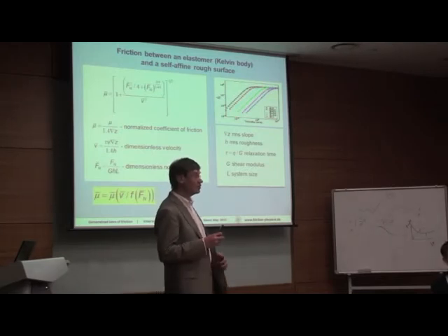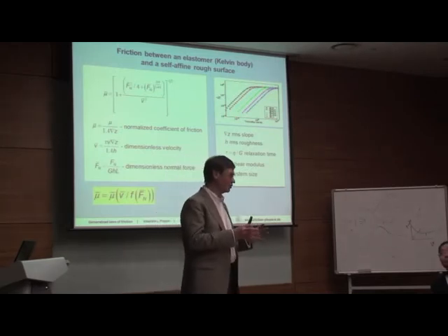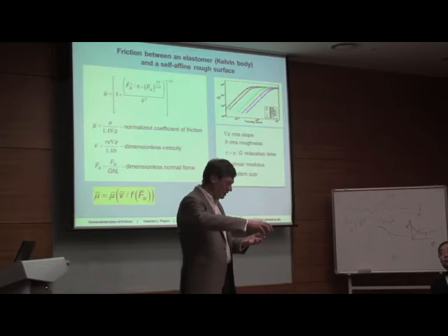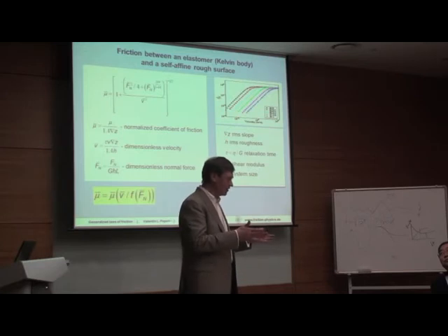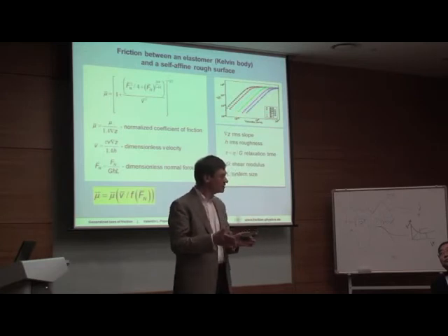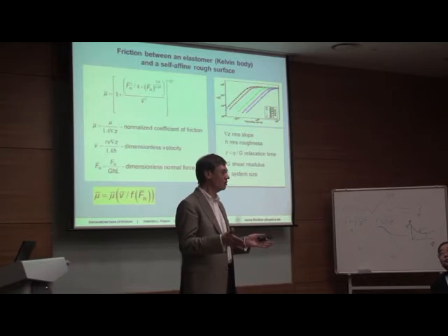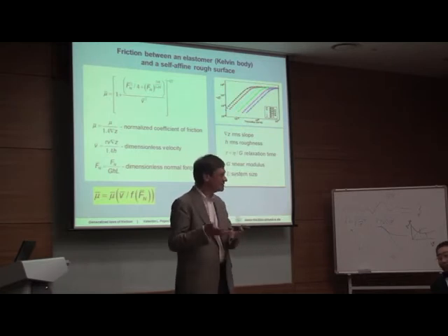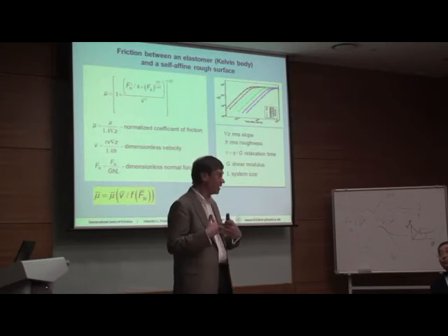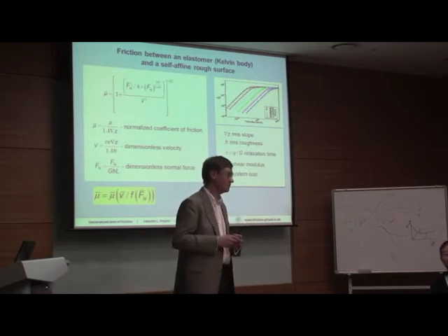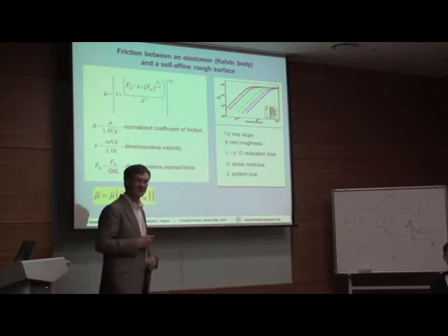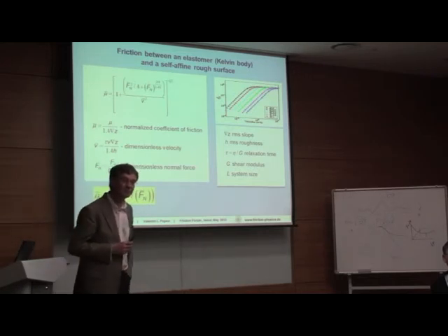I agree. The theoreticians, the nanotribologists who work with the atomic force microscope, have found that if you have no elastic instabilities in the contact, then you have no friction at all. It is averaged out. So you have to have unstable macroscopic behaviour to have friction. Otherwise, there is nothing. How will we validate that now?